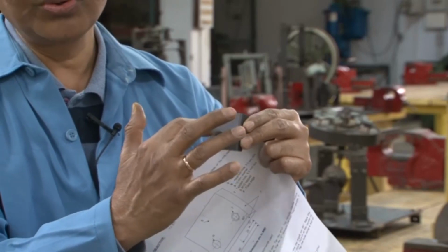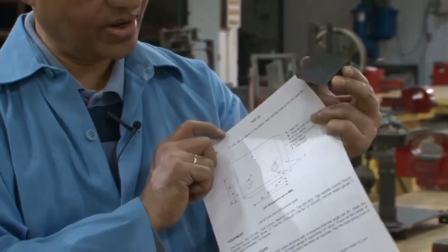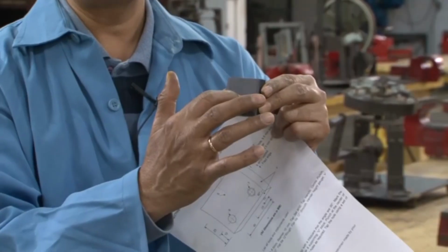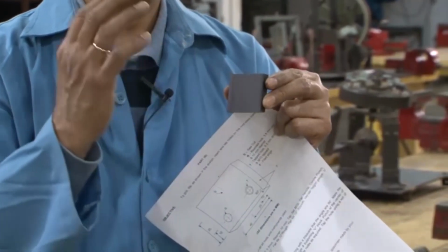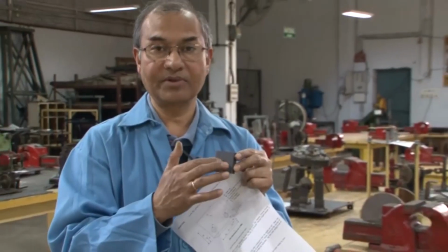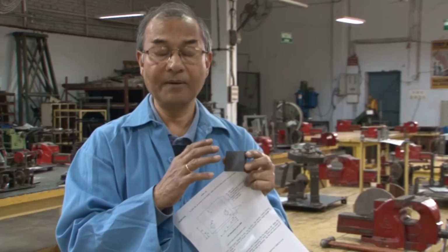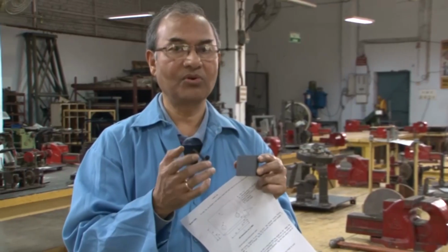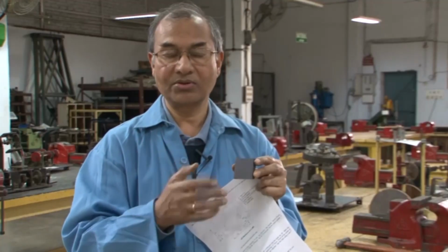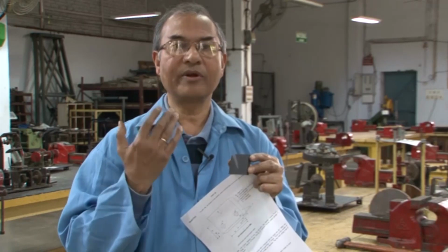So, there are two holes which are to be drilled, and on those two holes, according to the drawing, you can see that there are also threads. So, first the hole will be made with a drill, and I already told you that after the drilling the diameter of the hole will be slightly different from the diameter of the drill, normally a little more than the diameter of the drill because of the vibration of the drilling machine and so on. So, overall the accuracy of the hole is not perfect.